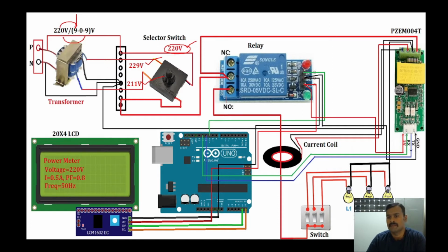Right. So here I have the energy sensor, where it needs the current input and voltage input of the supply or to the load what we are giving. So the same needs to be connected here. That means whatever the selector switch output which is going to the load, the same thing will be given to this energy sensor as well.